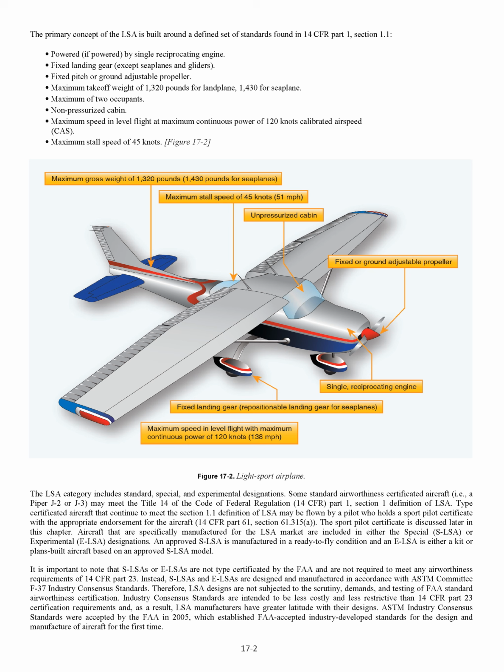Aircraft that are specifically manufactured for the LSA market are included in either the Special, SLSA, or Experimental, ELSA, designations. An approved SLSA is manufactured in a ready-to-fly condition, and an ELSA is either a kit or plans-built aircraft based on an approved SLSA model. It is important to note that SLSAs or ELSAs are not type certificated by the FAA and are not required to meet any airworthiness requirements of 14 CFR Part 23.